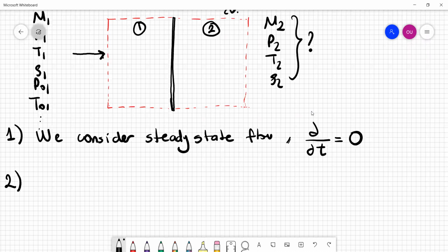And also we know that this is a shock wave. There is no external heat addition to the flow. There is, for example, a temperature change: the static temperature T2 will not be the same as T1, and we will derive the equation, but we don't obtain that temperature rise by heating up, like burning fuel or having combustion or anything like that. We don't have any of these. The flow is adiabatic, so although the total enthalpy of the flow remains constant, static properties do change.